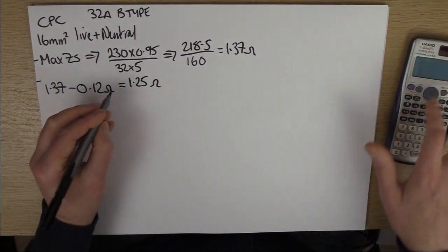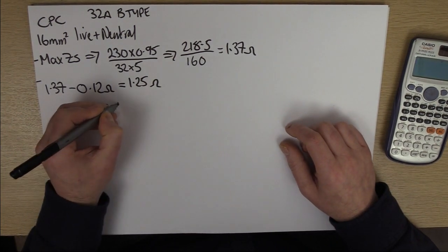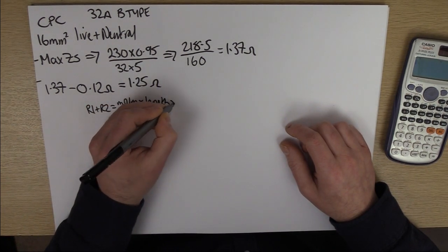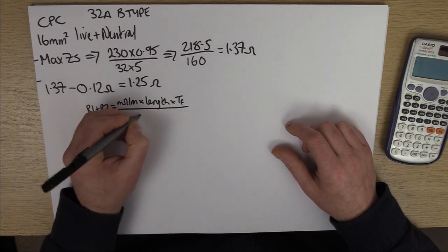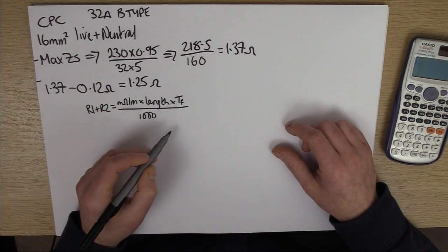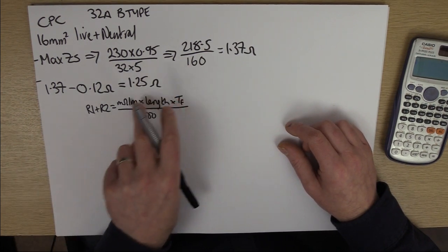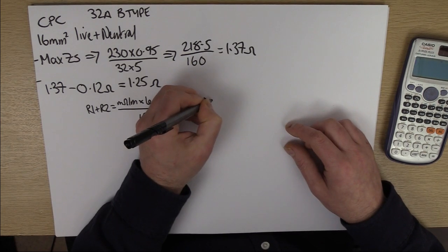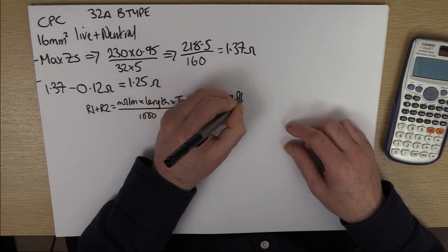Okay, now rearranging this formula, very similar to volt drop really. I'll put TF, temperature factor there. So that would end up there, they would divide down, and you end up pretty much with a max milliohm per meter.